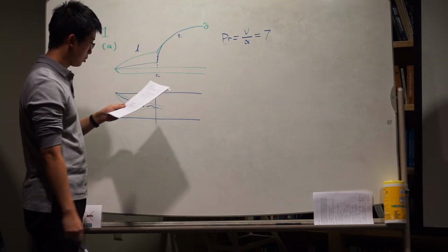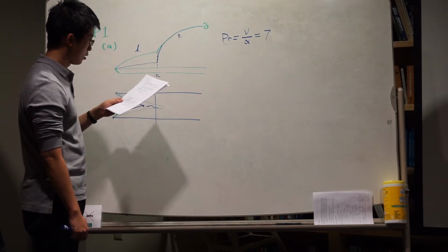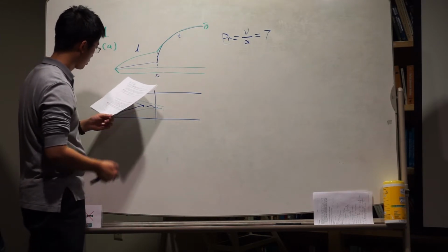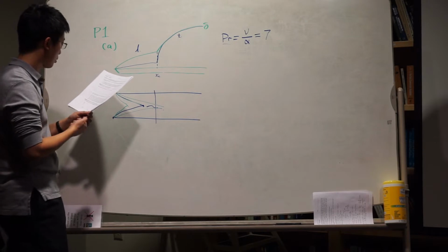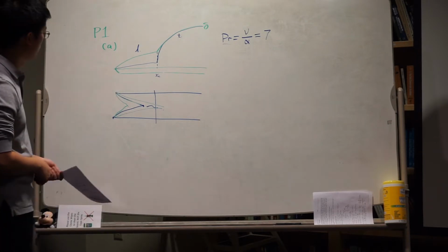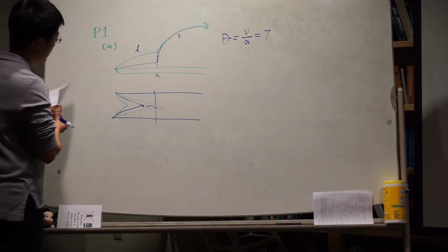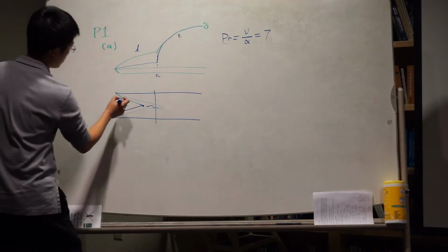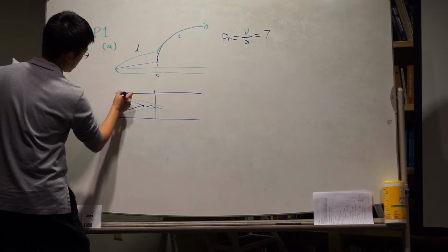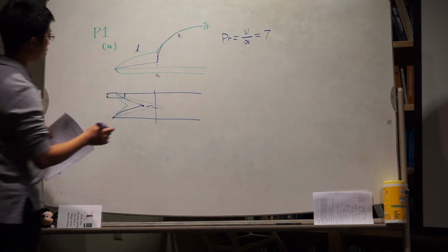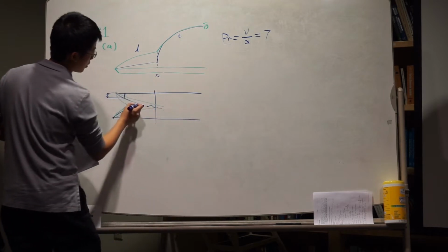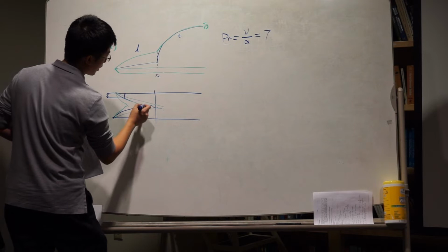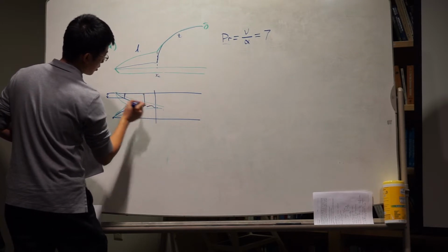And part 2 is asking about the Nusselt number, laminar fluid flow inside a circular tube. What is the average Nusselt number compared with the local Nusselt number? So we know when it's entering, the effective boundary layer thickness is thinner, right? It's this one. And when it reaches fully developed flow, after this, the boundary layers on both edges merge together, it's actually thicker.